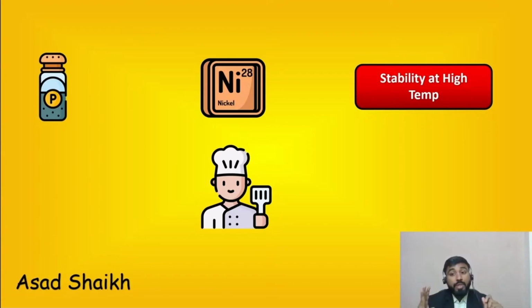The third important thing, when it comes to high temperature, is if you select dissimilar metals, if the trim is of a different material than that of your plug or your stem, each component has its coefficient of expansion due to heat. If they are dissimilar at very high temperatures, I'm talking about something like 600 degree, 800 degree, something of that level. There are certain applications which require such high temperatures. There you have to be very cautious if you are selecting dissimilar metal. You can have extra stress which can cause the stem to break or some other issues can happen in the plant.